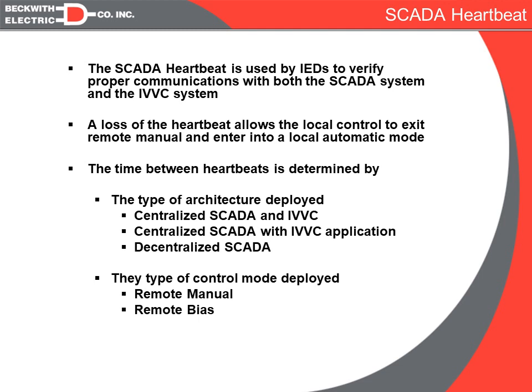So the basic definition of a SCADA Heartbeat is some sort of signal that instructs the local controls that they still are receiving valid communications from the Centralized Master. If we lose that heartbeat, then that is our signal to go into local automatic.